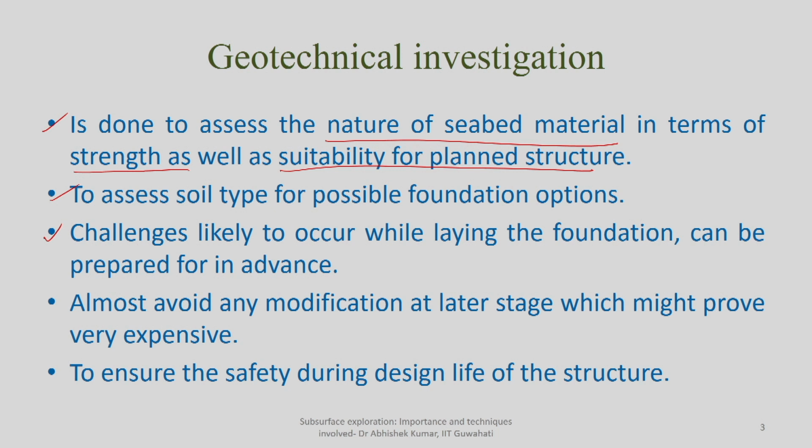Because, as I mentioned earlier, unlike onshore investigation, where depending upon the nature of the challenge you can at times alter the choice of the foundation or the investigation method, in offshore it is highly undesirable because the construction cost or investigation cost will be significantly higher, or the penalty will be significantly higher. So, it will be very favorable if we can identify what challenges are likely to be encountered during laying of the foundation.